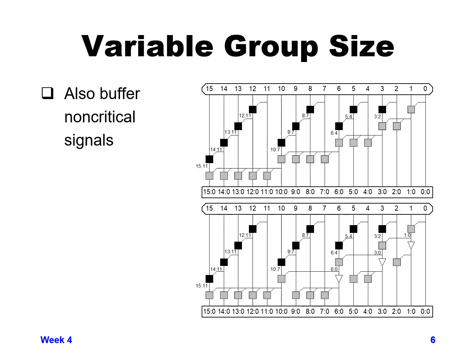But wait, we can do even better if we take the carry increment adder that we just talked about and now did a variable group size with that design. You can see in this, in the upper right, if we have the group sizes a little bit smaller on the right hand side as we're initially defining our carries, and a little bit larger on the left side, you can reduce our delay by 1 additional delay stage.